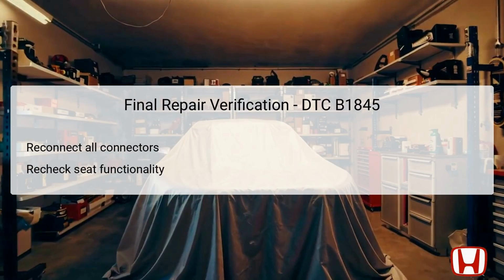Following reconnection, conduct a test function of the power seat recline switch to verify that the seat is operating smoothly in both recline directions. If the seat operates as expected without triggering DTC B1845, the repair can be deemed successful. This final check is critical for ensuring both safety and comfort for the vehicle occupants, as a malfunctioning seat can pose risks during driving.